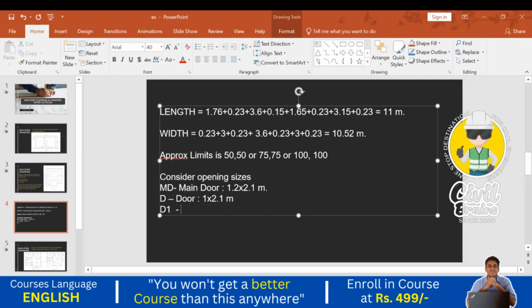D1 door, I just consider 0.75. Also we can consider 0.75 or 0.8. That depends upon the things, but most of the cases 0.75 to 0.8 we are keeping for bathroom doors. Okay, so the size of the bathroom doors is a little smaller compared with the bedroom doors. Okay, 0.75 just keep, and door sizes also vary. According to that you can provide.